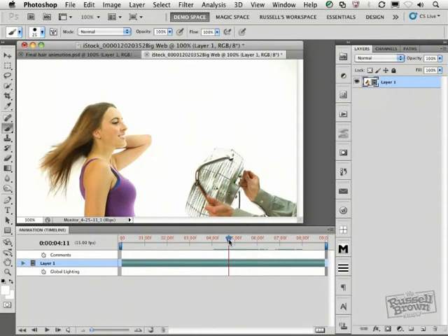Now that this is positioned, I'm going to move over here, as you can see my cursor, right over the work area start point. I'm going to click and hold and drag this over to the right. I'm now going to hold down my Shift key and snap it right to this start point right here. Did you see that? I first aligned this position and then I move my end point over.